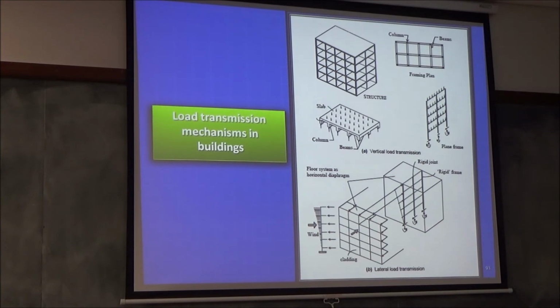You understand? Let's say you go to somebody's house and you're a structural engineer. You see a crack in the wall, one small 0.1 mm crack. The owner says, oh, what to do? You say, you better do something. But you fail to observe that there's a 5 mm crack in the beam, and the beam is a structural element, the wall is a non-structural element. You're making a big fuss about something that is not important. But in the beam, the steel has yielded.